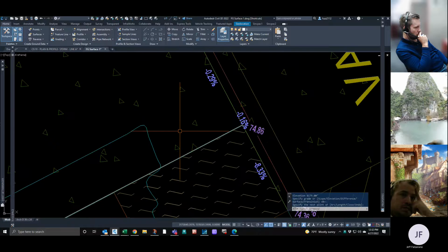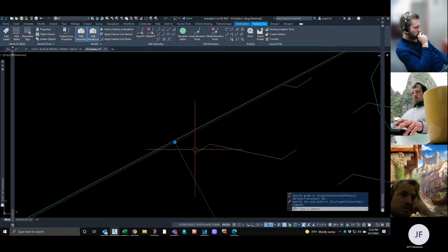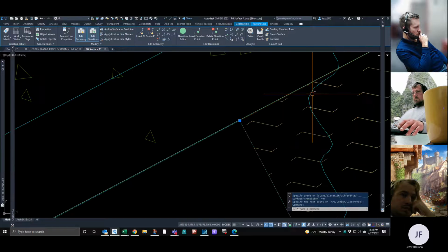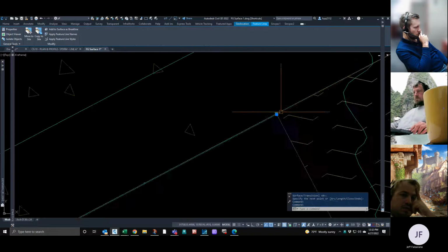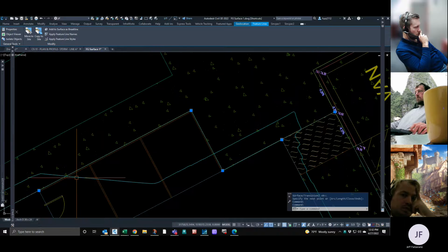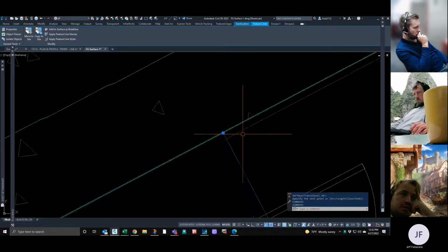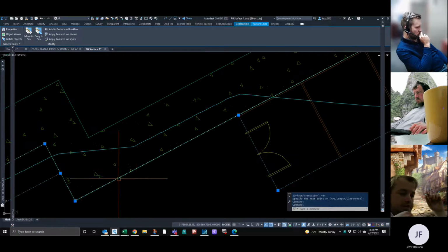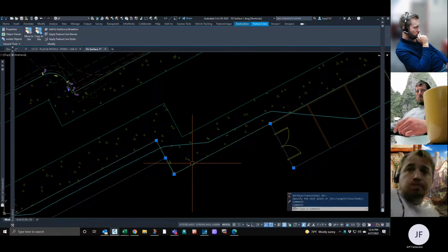So we have this finished floor elevation. If it's not matching that exact elevation where our sidewalk is coming in, then you don't want to cross this line. So that's why I dropped these points in a little short of the building. So we can put our own elevations in there and regrade this sidewalk however we need to tie into the doors and then actually slope away from the building so it drains off and there's no standing water.